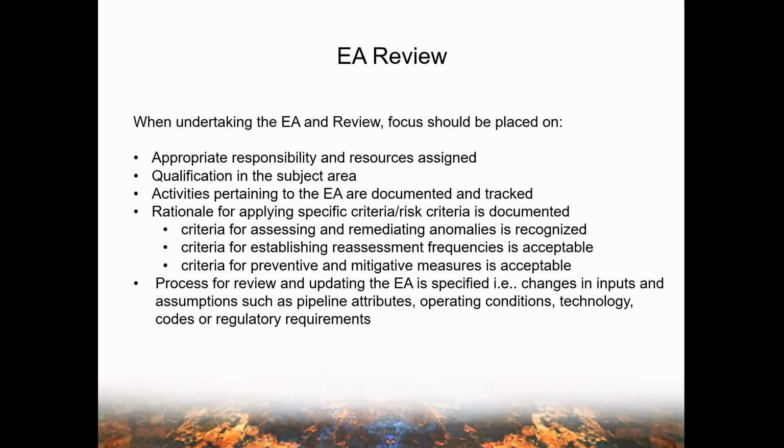I think as well, the guidance in Clause 3, Annex A, and the commentary speak to the rationale for applying specific criteria and having that fully laid out in your engineering assessment, whether it be the criteria you use for assessing anomalies or remediating them, the establishment of inspection frequencies, or putting forth preventive and mitigative measures. Also very important and highly suggested in Clause 3, Annex A, and the commentary is a process for review and updating of your EAs.